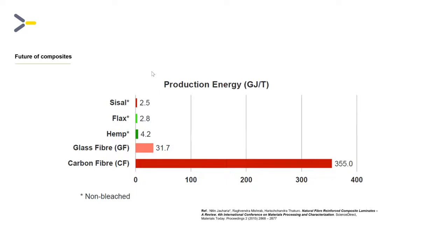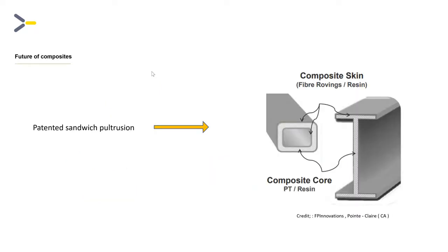But to combat this, when researching for this PowerPoint presentation on sustainability, I found a paper where a patent in the United States was granted to patent seekers on making pultruded sandwich elements with the core material being natural fibers, and the skin layer being more traditional fibers. This will solve a lot of the issues of water migration, but also give you a very strong and stiff outer surface, with the profiles optimized by weight and strength relations as well. This could be one of the options for the pultruders to work with more natural fibers in the future.